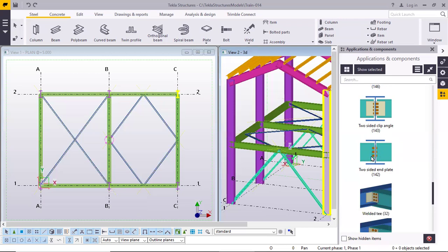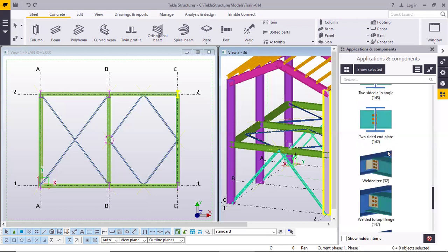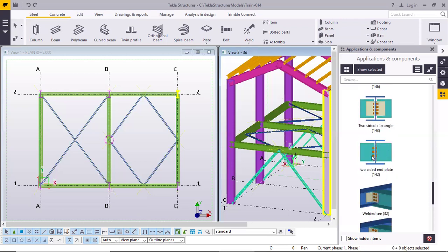The same condition appears here also, because here there will be one plate, there will be one plate, and there will be a common bolt. But if you give a separate connection here and a separate connection there, then the bolt will clash. This connection's bolt will clash with the other beam. So that is the reason we have a common connection for common bolts. Normally these two connections are there for the common bolt feature.